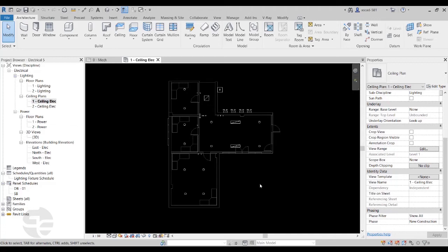Revit 2021 has come up with an enhancement where the property for switchboard is changed to maximum number of circuits instead of maximum number of single pole breakers, so that now we can connect more than 4 3-phase loads on a switchboard.